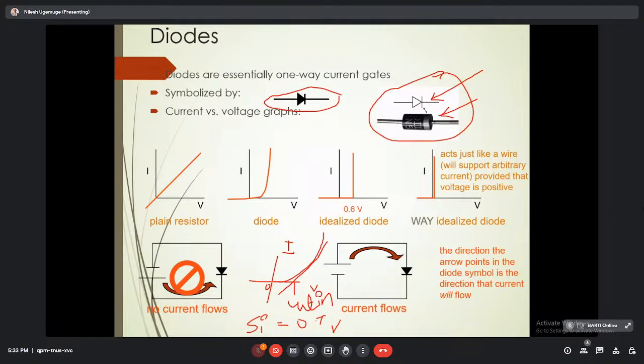Again, if we see the reverse bias, the forward current is in milliampere and the voltage is in volt, but the reverse bias current is always in microampere. Very little current flows through the diode when it is operated in reverse bias mode. That is why we can say this diode is not made for reverse bias. This diode is made to operate in forward bias, not in reverse bias.